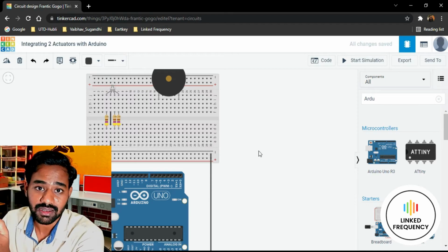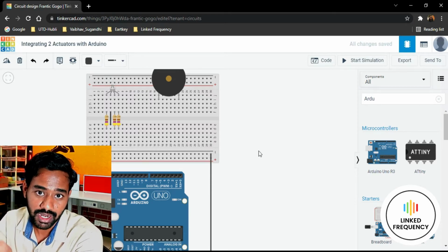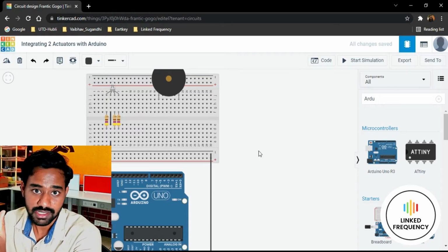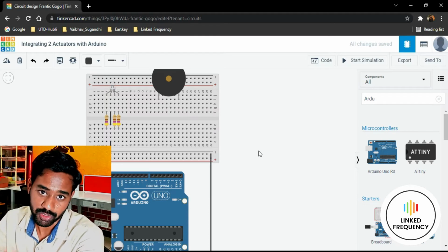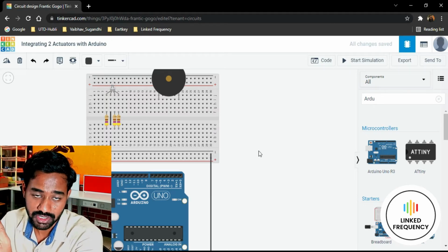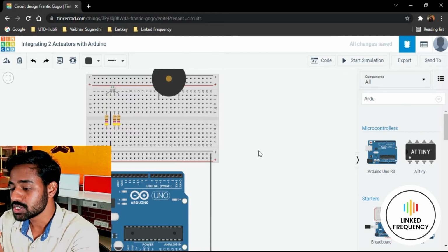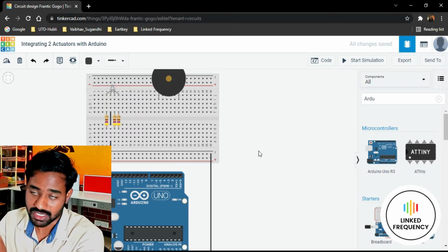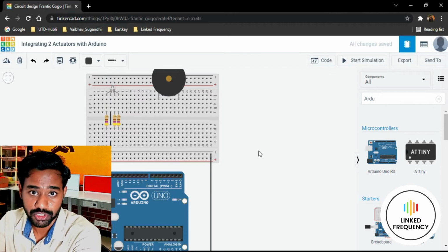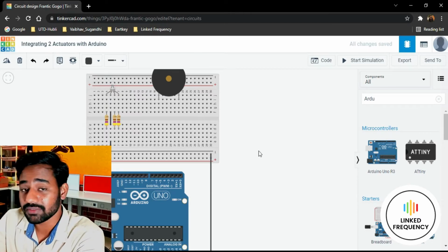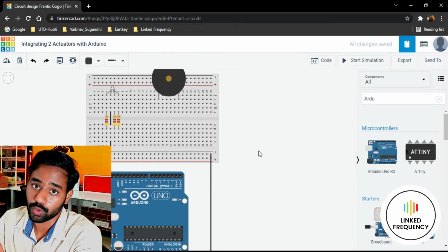When you are using a high potential to turn on and a low potential to turn off, in the direct sense, then you are using active high configuration, because to activate that particular actuator you are using a high potential. That is active high configuration. In reverse, when we use a low potential to turn on or run that actuator, then we are using an active low configuration.